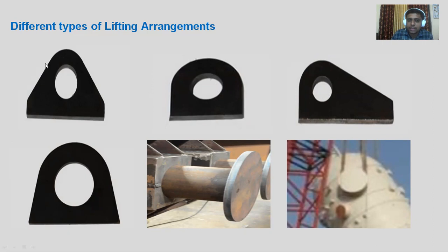we can see the area available between the edge and the hole edge is called the ligament. That is lower over here, and that is higher over here. So this one has the higher ligament and higher shear area, so it will give you higher shear strength.